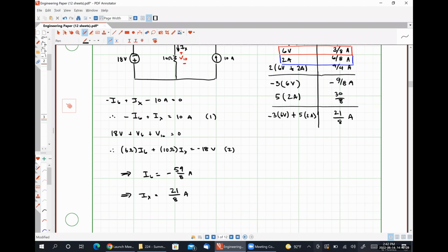Effectively, with the scaling property or with the homogeneity property, we can work a circuit with any voltage source value or any current source value that we feel like and determine what would happen if we scaled that up to whatever we were asked for. We are going to use this principle at several points throughout the rest of this class. So I just wanted to introduce it to you formally, rather than hand waving it when we use it later on.